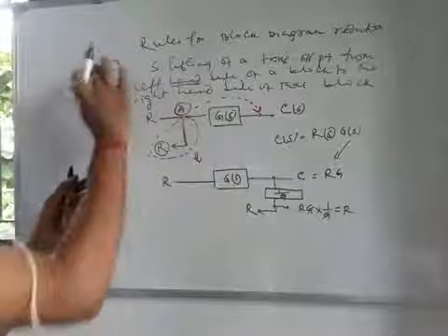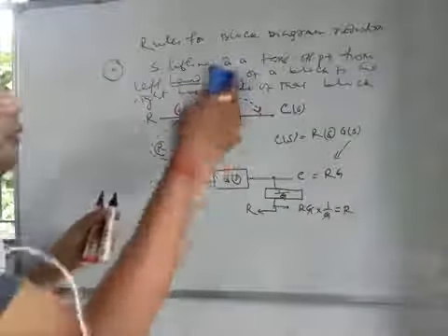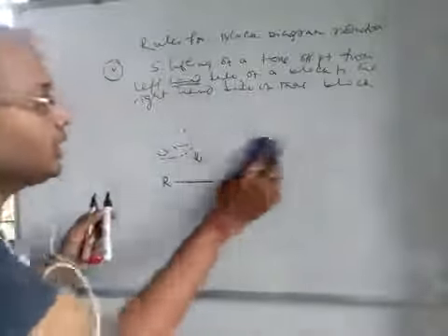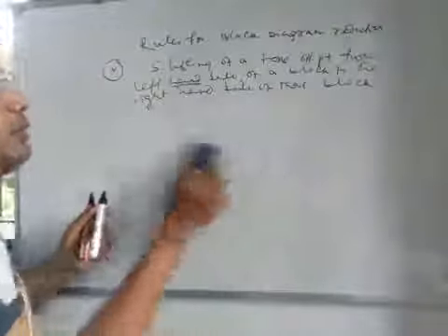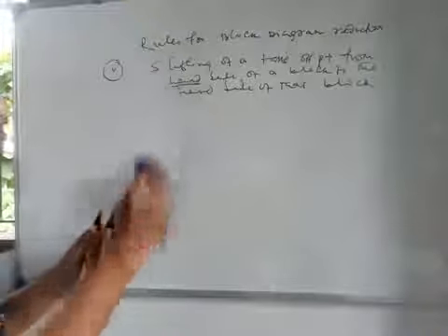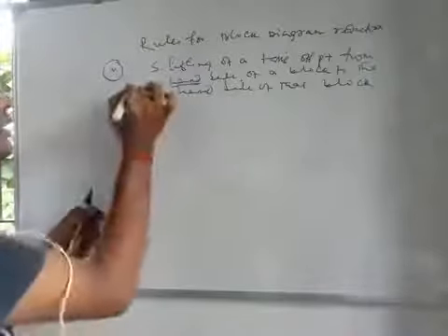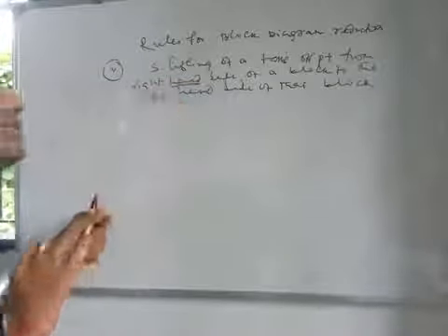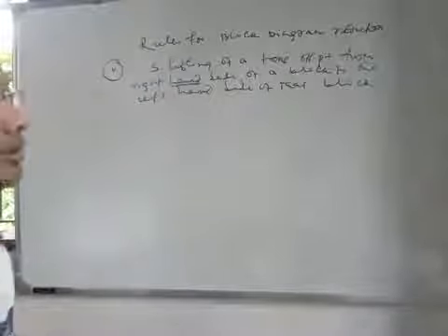Next rule is that we will shift the takeoff point from the right hand side of the block to the left hand side of that block.